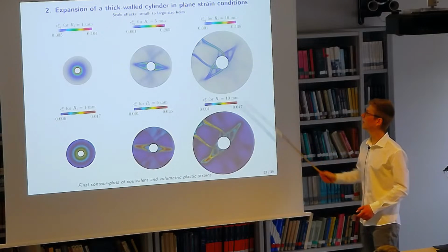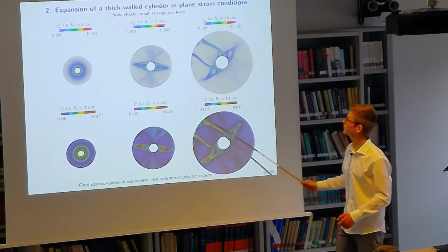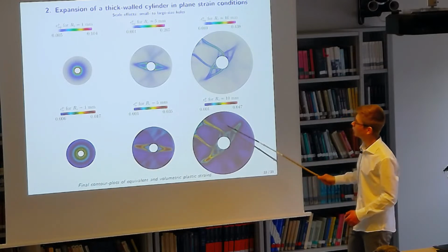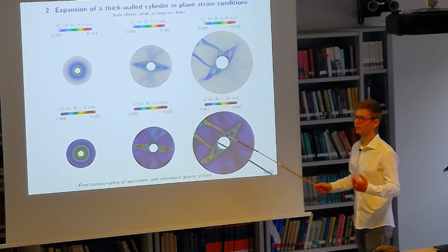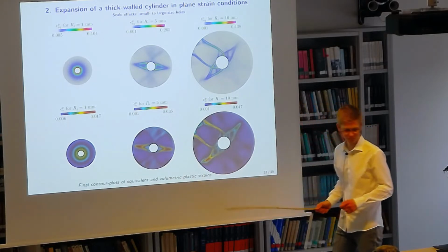At the same time, and as in the experiment, you can observe that there is an increase of the volumetric part of the plastic strain inside this shear band, which is the consequence of the fact that the Cam-Clay model is predictive of softening in case of dilatancy.